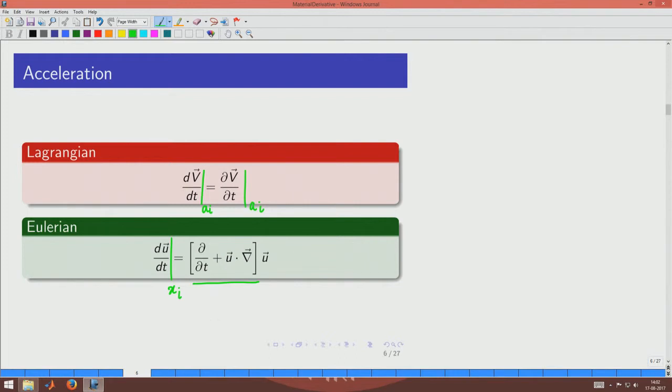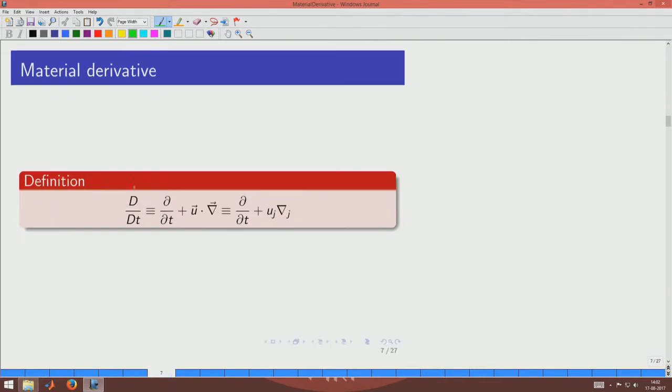Okay. And because we are going to use this as default for all our expressions, it may be a good idea to not use the same symbol for the complete differential with respect to time. So, we use a new symbol, so that we remember this particular additional term every time. That is why we introduce a new symbol here, capital D, and what we want to refer to is as material derivative.